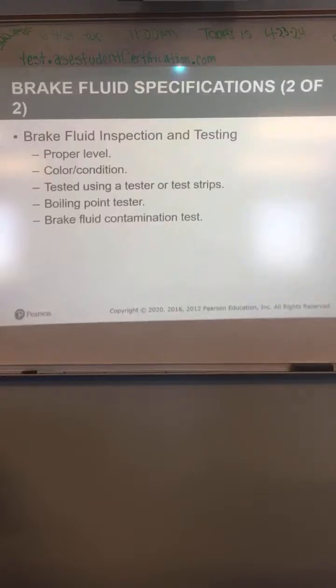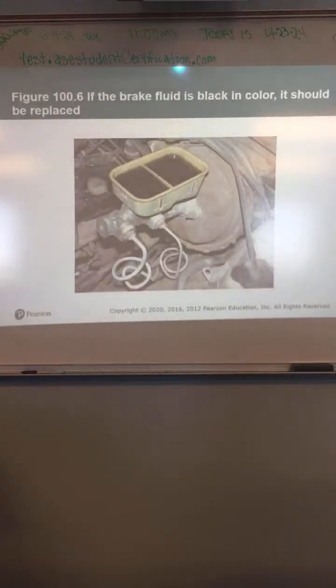A boiling point tester or a contamination test, you're not going to do that. Probably the most you would ever do is maybe use a test strip. And all that does is you just stick it in the brake fluid and it will give you an idea of its condition. It should not look like that. The brake fluid should have been flushed on this one a long time ago.